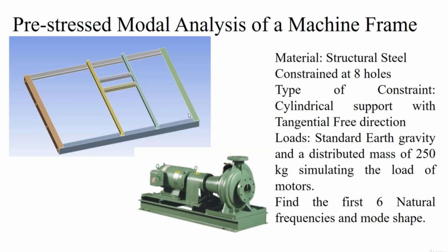We need to constrain using the cylindrical support by leaving the tangential direction as free, and we are also going to add standard earth gravity and a distributed mass of 250 kgs for performing the pre-stressed modal analysis, and we are going to find out the first 6 natural frequencies and mode shapes.